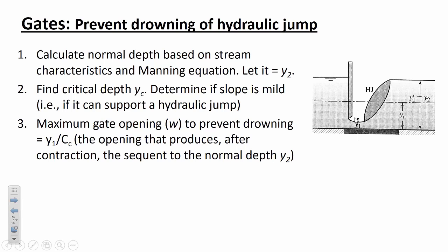All right, now problems like this often ask, how high could the gate be opened? If you open that more and more, it's going to be getting the hydraulic jump closer to the gate. Because if I close this down more, then that's going to have a smaller Y1, and it will have to jump up at a deeper Y2. So as you pinch the gate closed, it pushes the hydraulic jump away from the gate. But as you open the gate, that draws the hydraulic jump towards the gate.